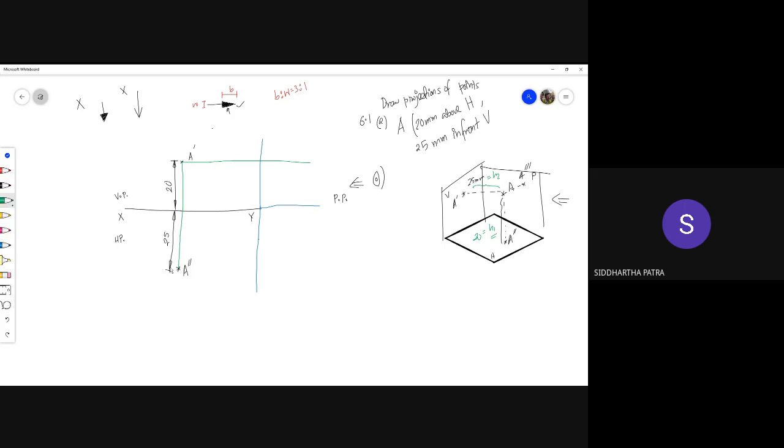And for the distance from the vertical axis, that is by how much it is in front of the vertical plane. So you need to draw this line right here, okay. And there are two ways we discussed. One was to draw a line which makes an angle 45 degree with any of the horizontal or the vertical lines. So that way, when you extend this line,